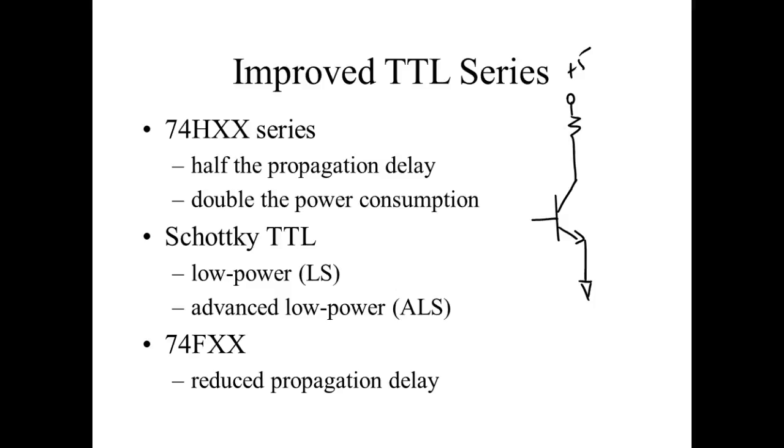We're either turning these transistors on, or we're turning them off. Now, when you take solid state, we'll spend more time in the active region because that's when we can amplify stuff, right? So when you got a stereo out there, we're not cutting on and off, we're operating in the active region. Your outputs are. We can do a lot of digital stuff on the front end, but by the time it hits those speakers out there, we got to be in the active region.